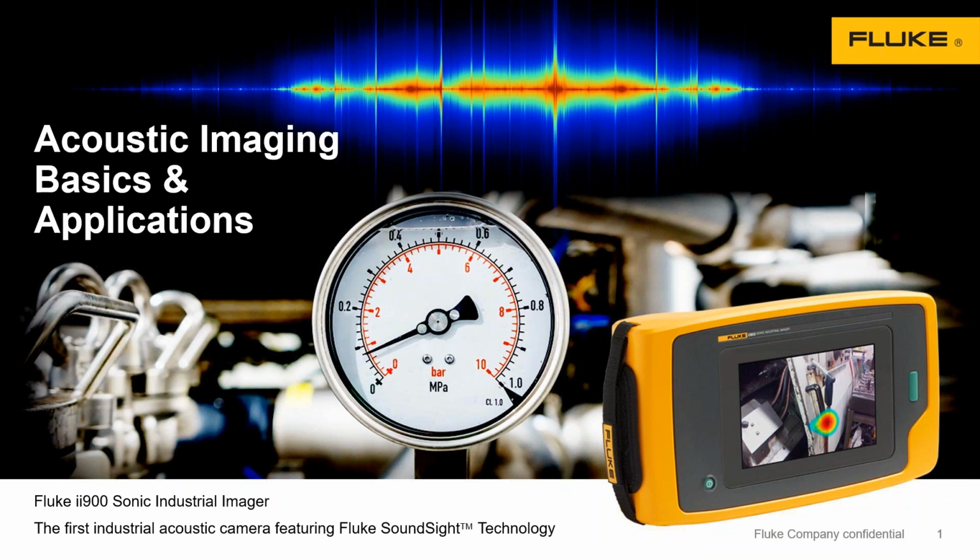But the bigger picture of it is somewhere in that facility, there's a compressor that's using a whole lot of electric power to actually keep the system pressurized and keep everything running. And if you've got a whole bunch of losses somewhere down the line, even if they're a whole bunch of small losses, they add up to almost a big, like a 4-inch pipe worth of air that's just leaking out.